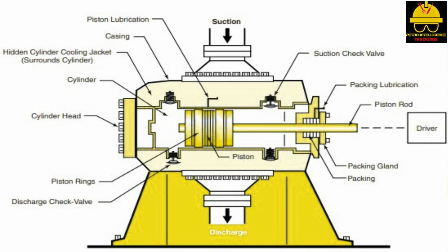Pressure differences of below atmospheric on the suction side to over 30,000 psia on the discharge side are possible. During operation, reciprocating compressors perform best with clean gases. Entrained water, dirt, and impurities will cause excessive wear on the piston and cylinder. Reciprocating compressors are selected when low flow rates and high discharge pressures are required.